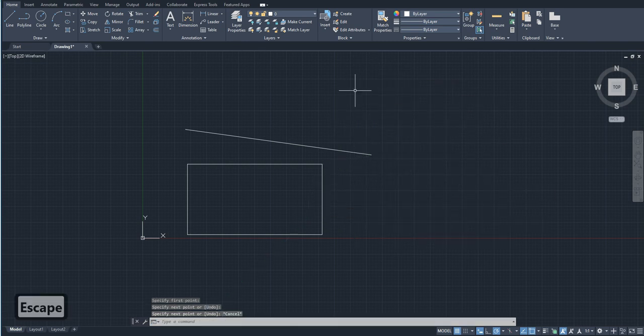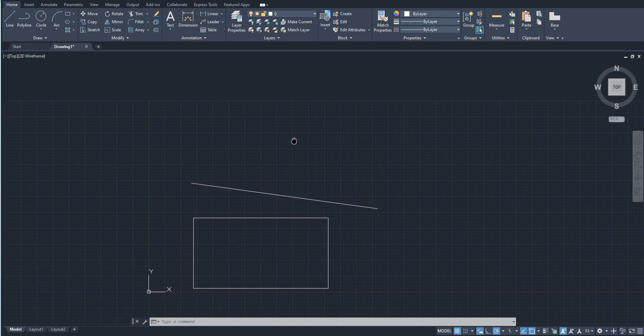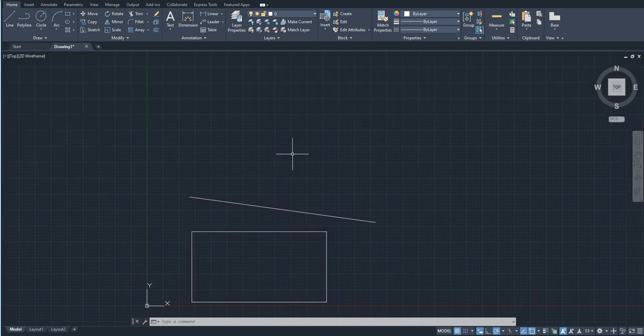That ends the command. Now we have drawn a line over here, but as you can see, it has no specific dimension or direction. For now, I'm going to teach you how to draw a line with a specific direction and dimension. I'm just going to move the workspace a little down to create more space, and click on the command line. Now it's asking me to specify the first point again.